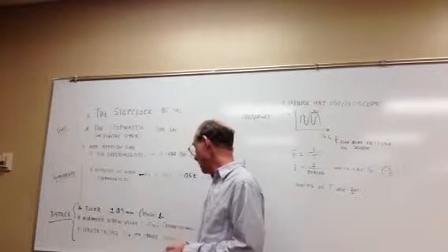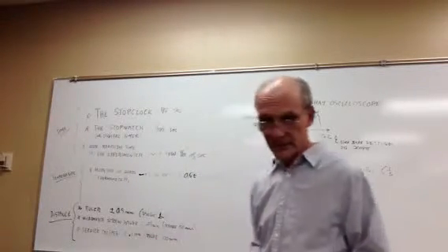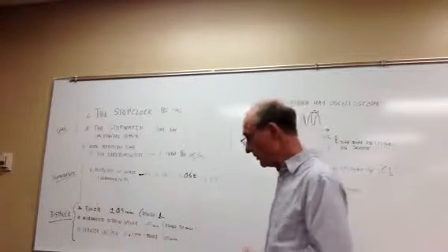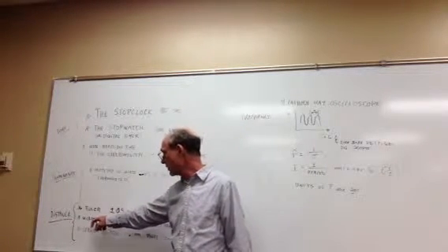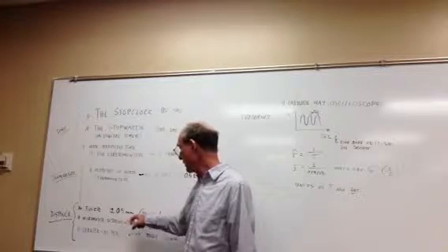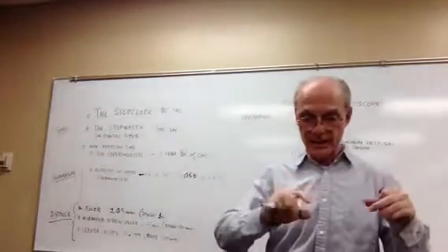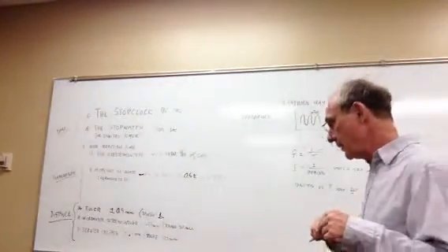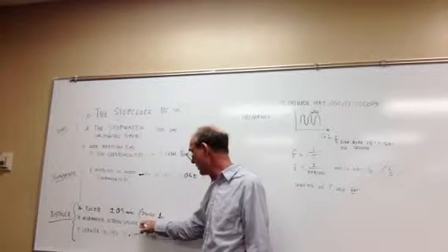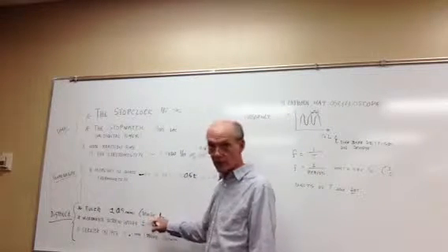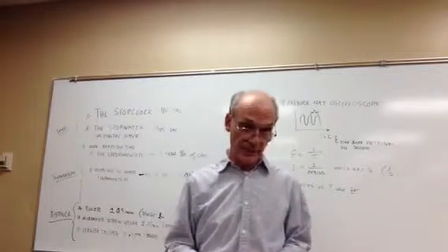But if you're interested in a more, and I'll use the word precise now, and then give me 5 minutes and I'll explain these terms more precisely, then you might want to use a so-called micrometer screw gauge, which is a device that is built like a horseshoe, and it has a screw on the side, and it's graduated such that you can measure to about plus or minus 0.1 millimeter over a range of about 50 millimeters.